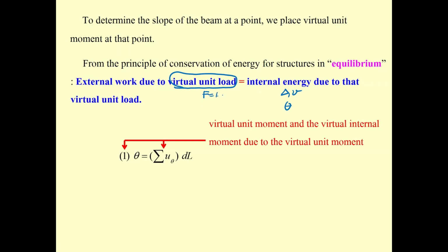This is a force of 1.0 unit to determine the deflection. But if you would like to determine the slope, you have to put the virtual moment. This one is the virtual force, and this one is the virtual moment. Now, if you determine the slope over here, this term will change to small m.